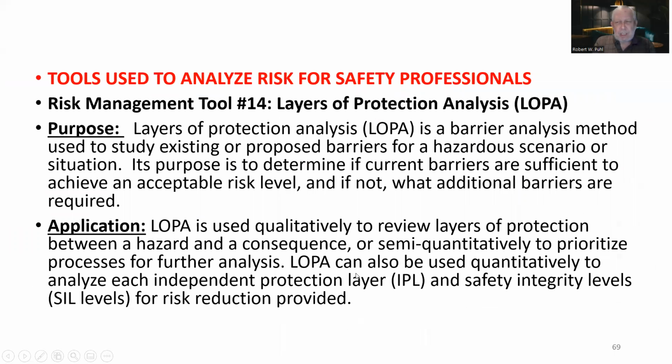14, layers of protection analysis. Layers of protection analysis is a barrier analysis method used to study existing or proposed barriers for a hazard scenario or situation. Its purpose is to determine if current barriers are sufficient to achieve an acceptable risk level, and if not, what additional barriers are required.